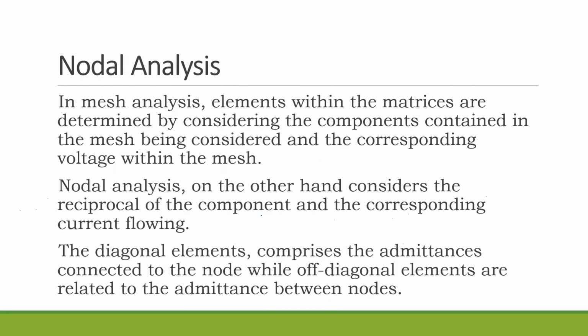So, nodal analysis. Just now, for the mesh analysis, we determined the elements within the matrices by looking at those contained in the mesh being considered and the corresponding voltage within the mesh. For nodal analysis, we're now going to look at the reciprocal of the element and the corresponding current which flows.